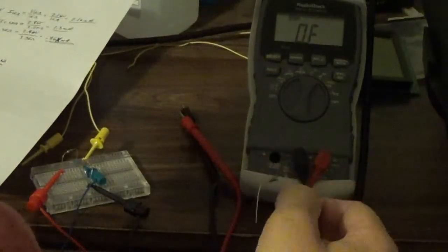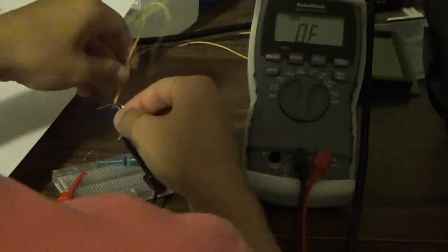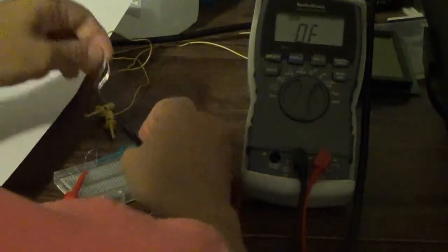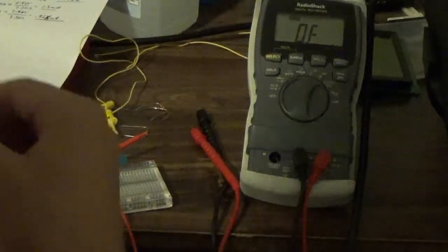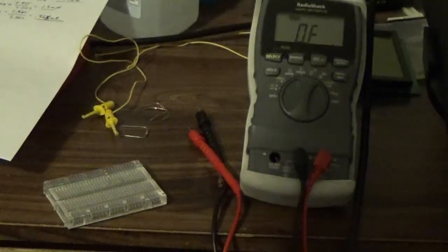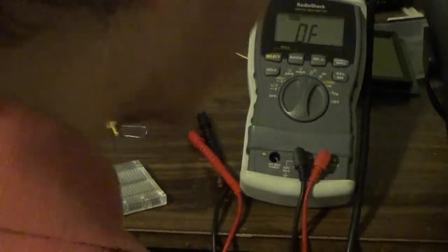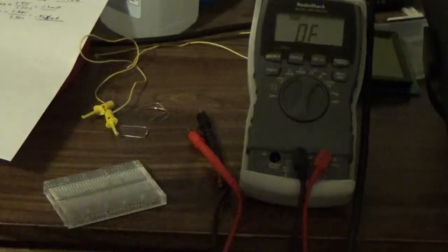So, remember what I was talking about with power ratings before in a circuit. If we exceed the power rating of something, it does bad things. So I'm going to show you what bad thing it does. Where'd my 300 ohm resistor go? Orange, black, brown. That should be 300. Yeah, that's it. So this is a 1/4 watt resistor right here, a through-hole resistor. And if we apply a voltage greater than what it can tolerate, it will blow up.